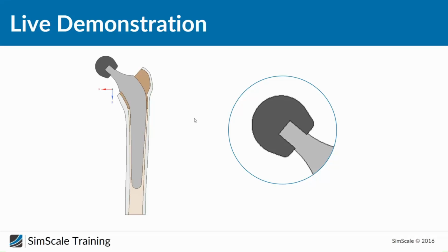Shea wants to know that bone material is mostly nonlinear with composite-like behavior. Is that possible to model in SimScale? Yes, basically we can also model non-isotropic or anisotropic materials, as I showed you. But for example, composite models with shell are not possible. But again, the material model parameters we used were based on a paper about a simulation, which was published at a conference, and they did in the end the same approach, and results show that it's good enough. So simulation is really often about simplifying things, making it as simple as possible.